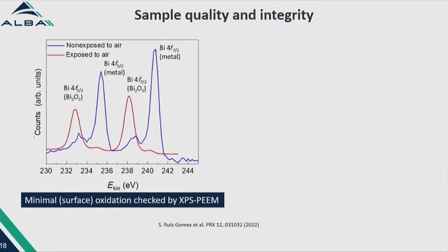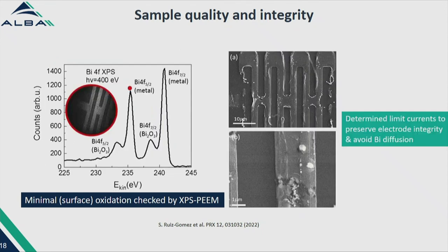And also, of course, before doing an experiment, you have to determine what is the maximum current you can apply before you blow up your electrodes, and more subtly in this case, at which temperature, which is already 90 or 100 C, so quite low, you start to have bismuth segregation to the surface or clumping. Then in this case, we don't have bismuth-doped copper anymore. We have copper with inclusions of bismuth. It's not the same material.